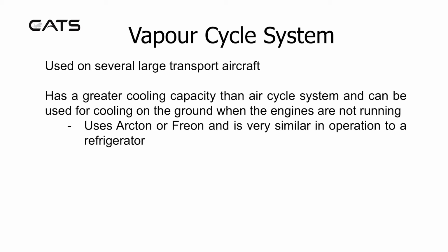It's used on several large transport aircraft. It has a greater cooling capacity than the air cycle system and can be used for cooling on the ground when the engines are not running. It typically uses arcton or freon and is very similar in operation to a refrigerator.